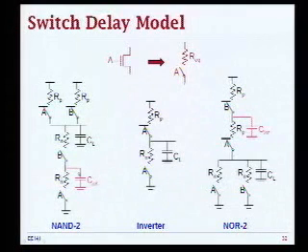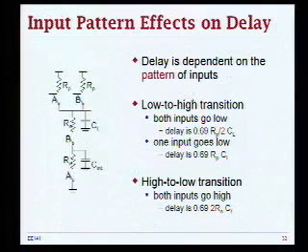Now you see that you also have this intrinsic capacitance. This complicates the analysis a little bit, but we can still use the same engine we are familiar with, the Elmore delay analysis, to figure out, at least to a first order, what are the parameters that affect our performance. And most of the time, for the first cut sizing of your gates, you simply ignore this intrinsic capacitance, because you say, well, let's worry about it later. It's not really dominant. Let's try to figure out the dominant factors that contribute to my delay. That's what we are going to do next.